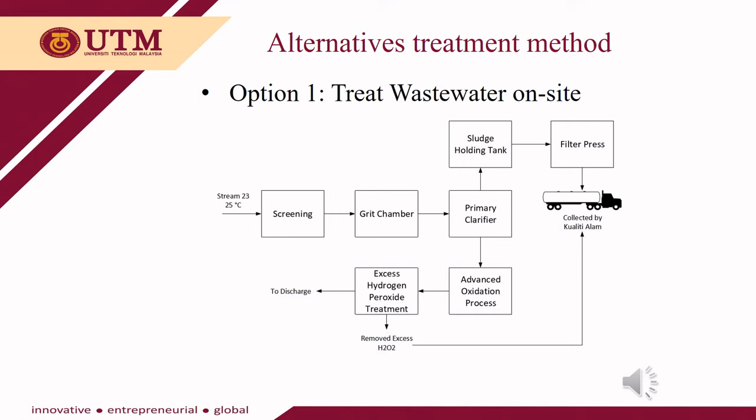The water that has been freed from suspended solids will proceed to the advanced oxidation process to remove methanol from the water. The water that has been freed from methanol will proceed to hydrogen peroxide treatment to remove excess hydrogen peroxide by an adsorption process using granular activated carbon.